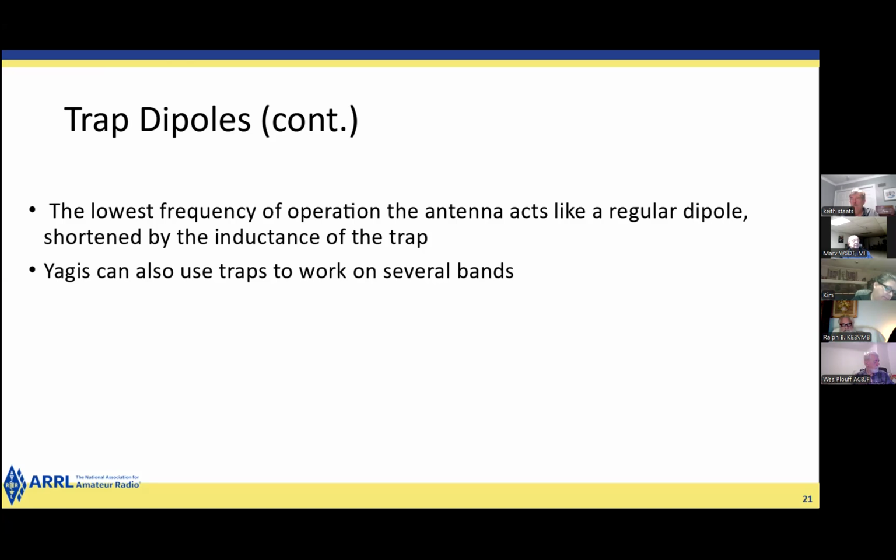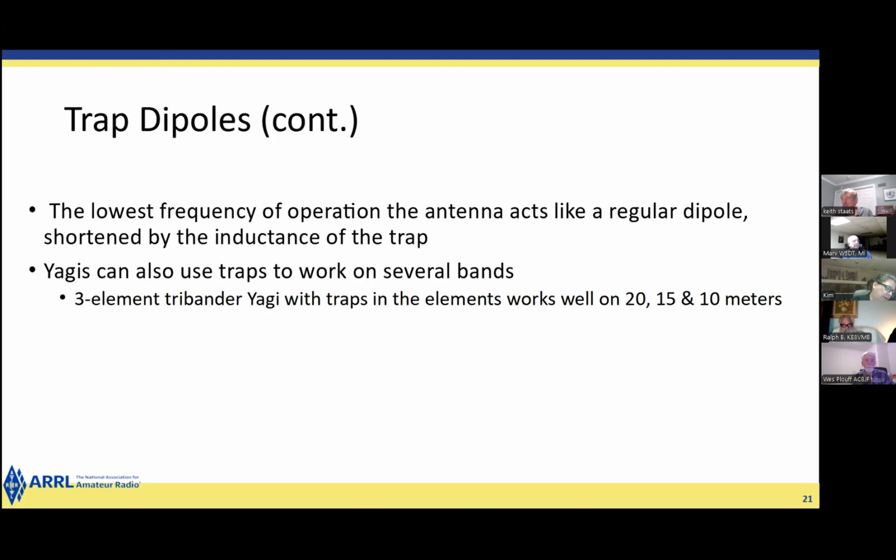Now, Yagis also use traps to work on several bands. A 3-element tri-bander Yagi with traps in the elements works well at 20, 15, and 10 meters. In fact, I've got one. It's in pieces behind my garage.